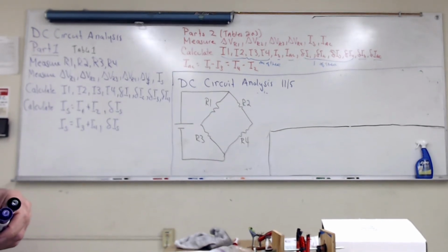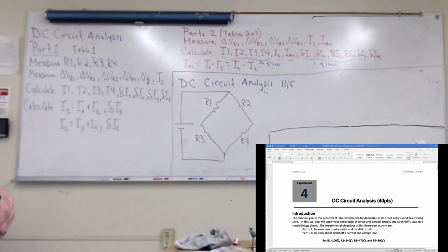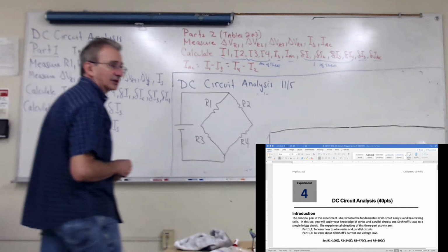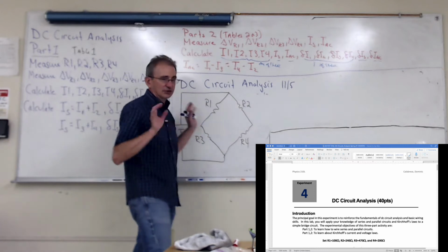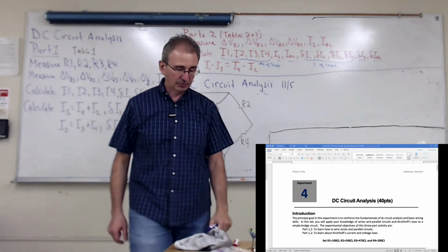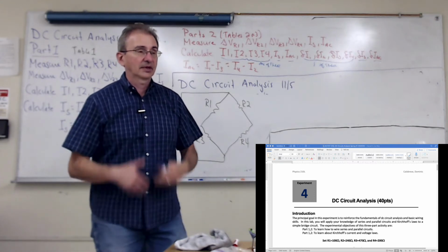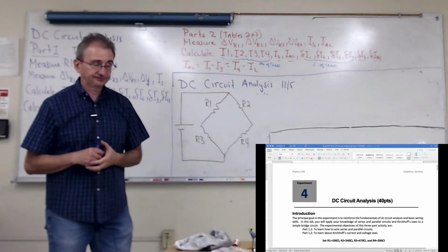And in this lab, what we're going to do is verify Kirchhoff's current rule. And granted, this first part of the lab, this circuit you can analyze using series and parallel. I understand that. But we're going to use it to verify Kirchhoff's current rule and the loop rule.